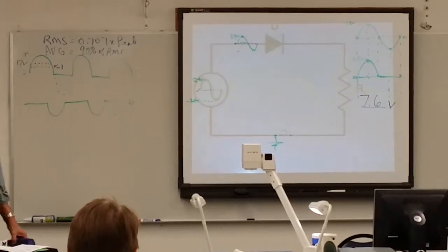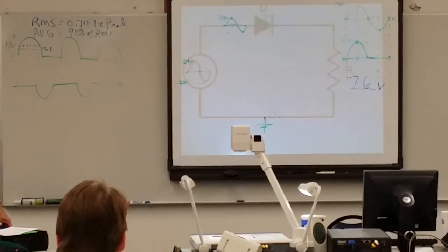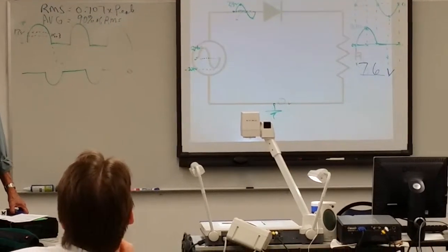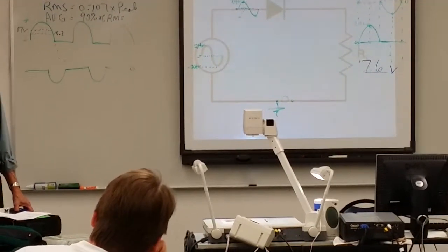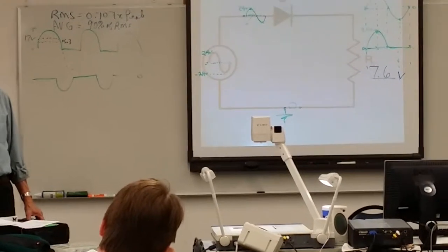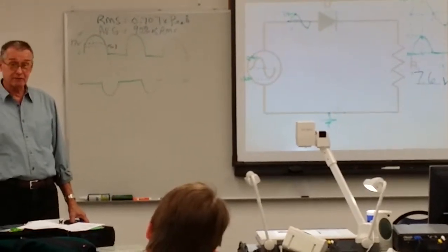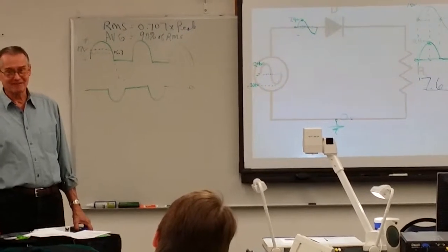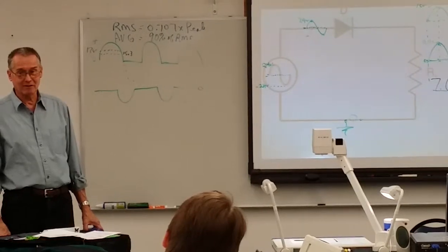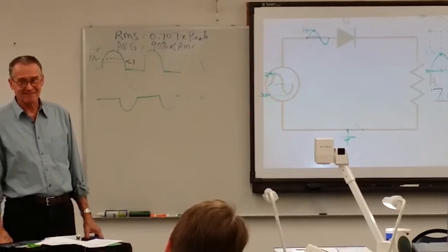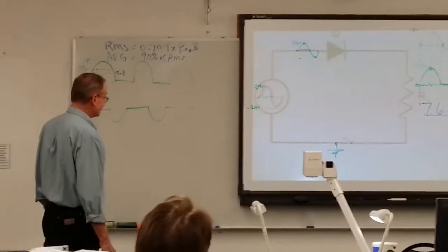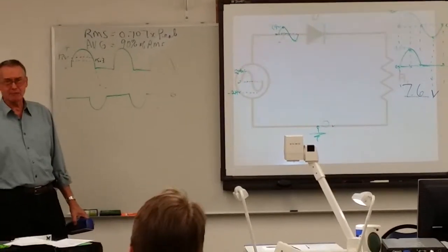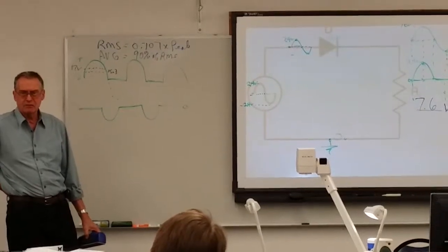So as long as you're not overloading with current, it'll be fine? Right. When you overload, you've gotta be putting a lot of current into them. You gotta remember, these are like 700 and 800 amp hour batteries. That means they can deliver 800 amps for an hour before they're dead. How long would it take to put 800 amps back into a discharged battery at 1 amp? A long time. At 1 amp, it'd take at least 700 hours.